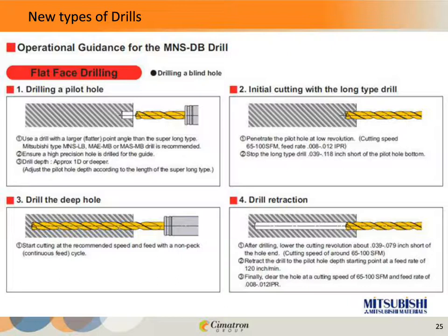Prior to breaking out, we want to slow down the feed rate, and then slow the RPM down as we come out of the hole. Then of course repeat this process. So this is going to require some unique settings for programming, because canned cycles don't really handle this type of operation.